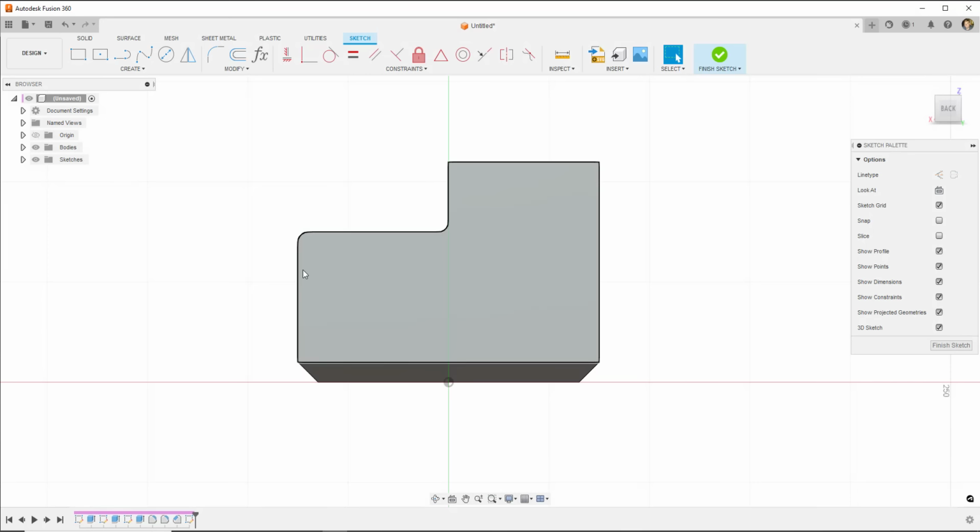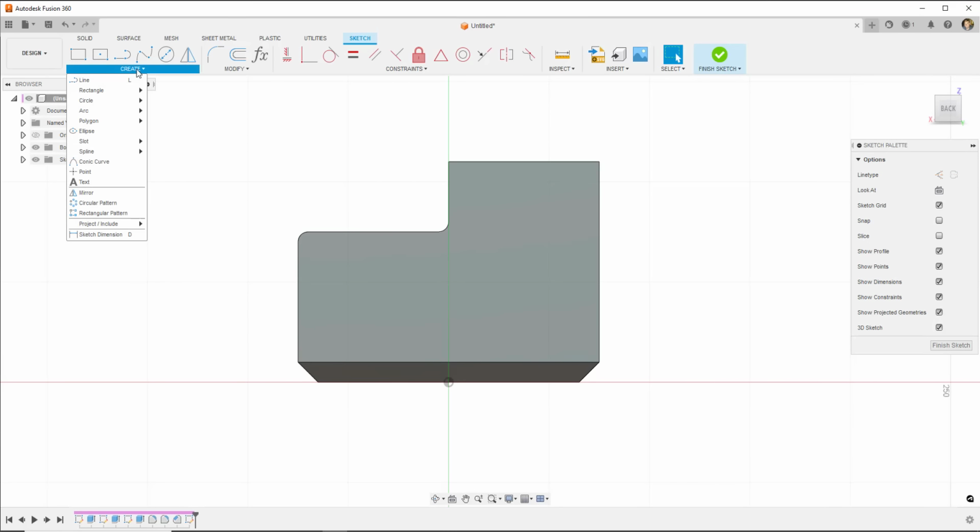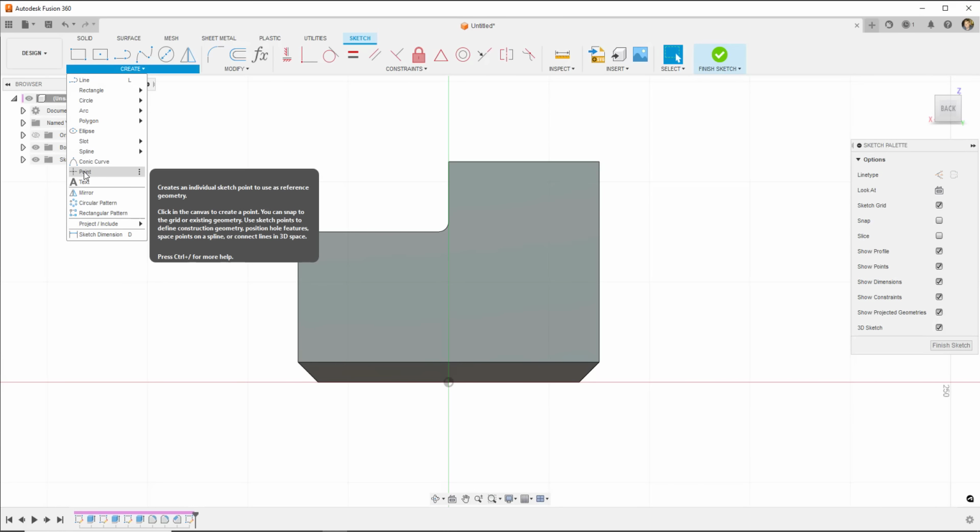Well, in Fusion, if you're going to do holes that are going to be used for something like, you do have a hole command, which it's good to use because you get a lot more functionality, and I'll show you that now. So first we just want to position the center points of these holes, and we can do that by just using these points here.